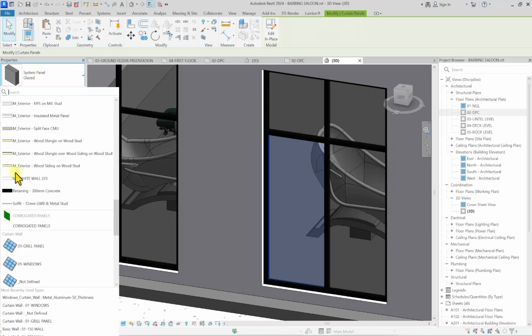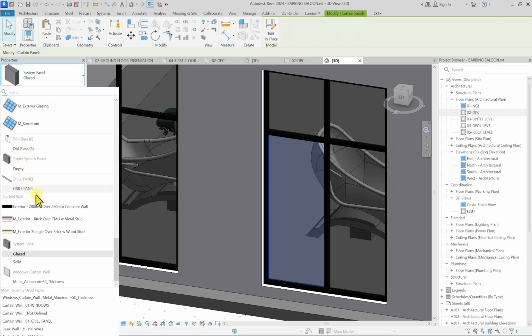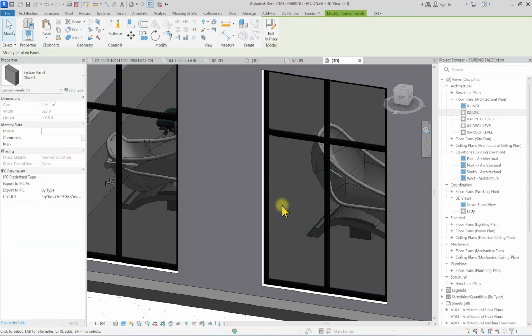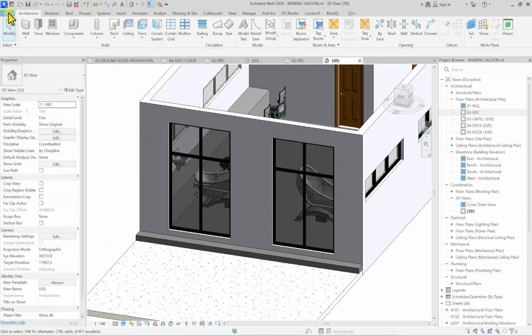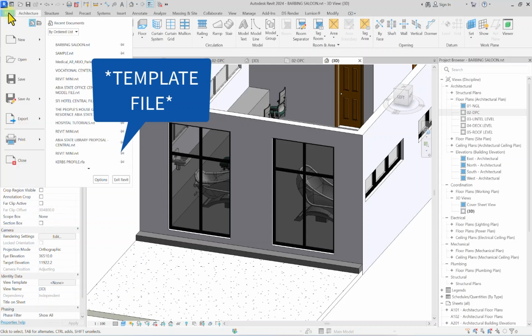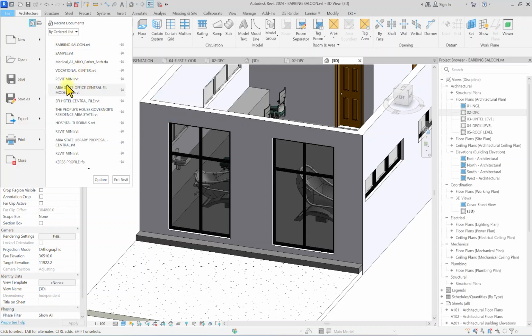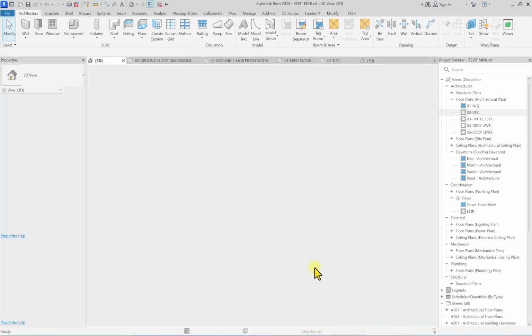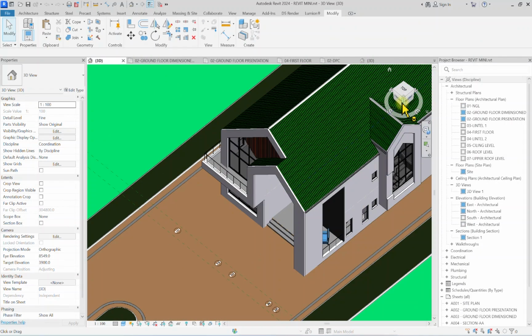So we only have a single swing cutting wall embedded door here. So we only have a double swing, sorry, but I think I'll prefer a single swing here. So I'm going to click on escape. I'm going to click on file, open our project file again and see if I can copy a single swing cutting wall embedded door. So I'm just going to open it. So after doing this, I'm just going to rotate this.